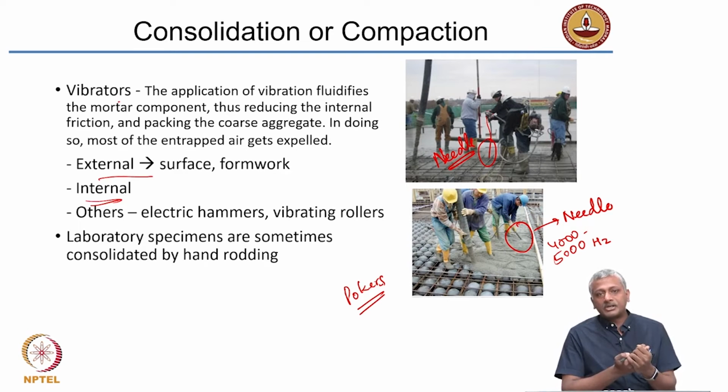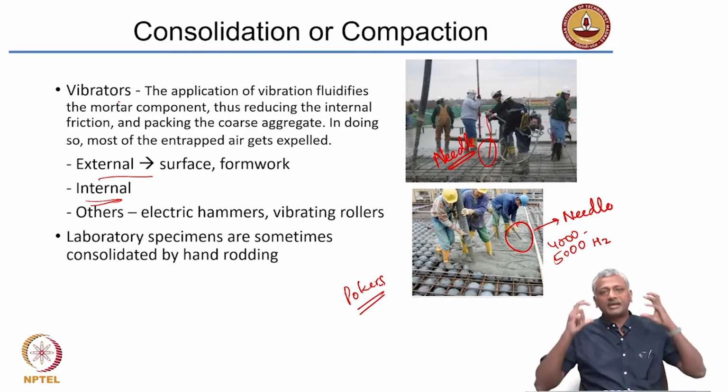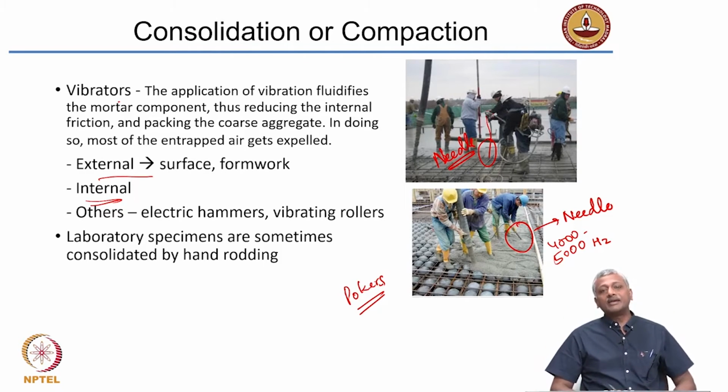Secondly, this vibration is a process that generates tremendous amount of noise. So if you are not protected properly by wearing earmuffs, you can have hearing damage. So vibration in a construction site is extremely polluting, noise pollution is very high from vibration. So you need to ensure that you keep vibration to a minimum, or try to use concretes which may not need vibration. Okay? Now, when you come to the laboratory, you don't always use vibrators to make your specimens.